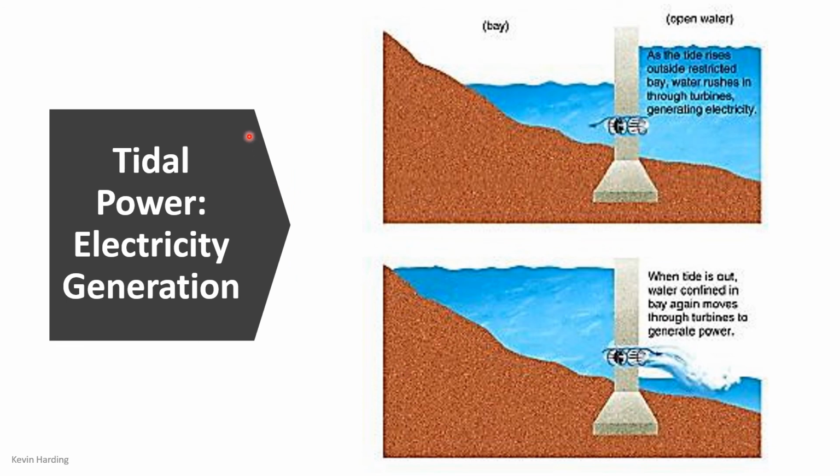So there are also systems like this. This is another example of exactly the same thing, where we're almost building ourselves a dam. You build a wall into the side, into the ground, and then this wall up here, so that when we have a high tide, the tide rises on the outside, and there's only one opening through here. So we have a higher pressure on the right-hand side because the tide is high, and all the water will push through and power the turbine.